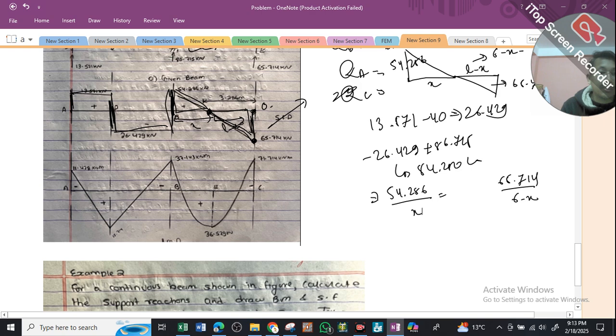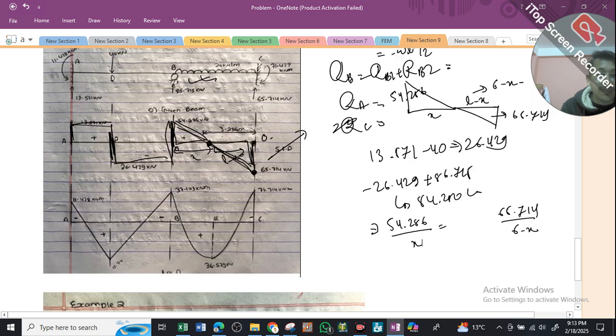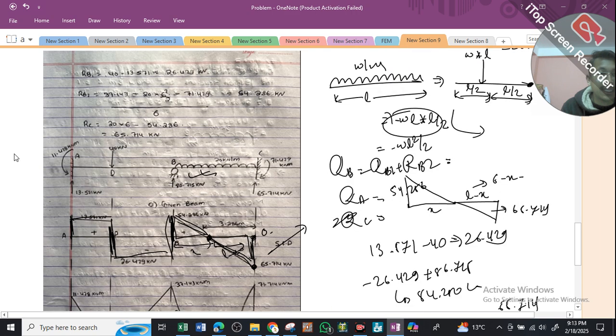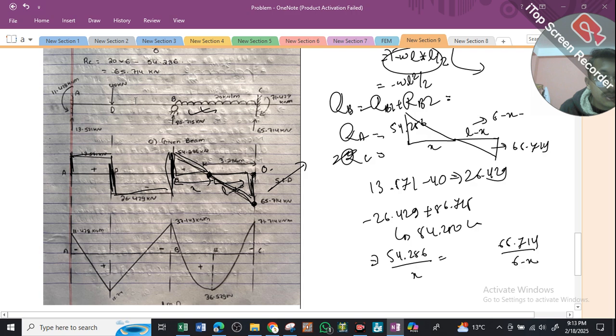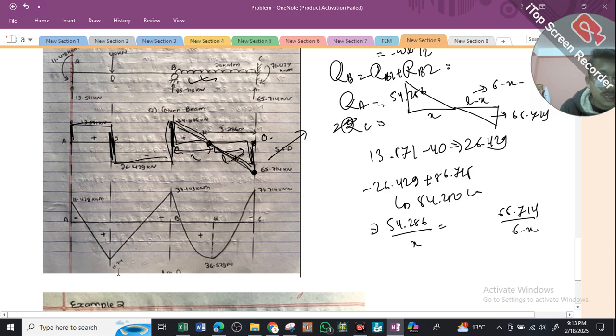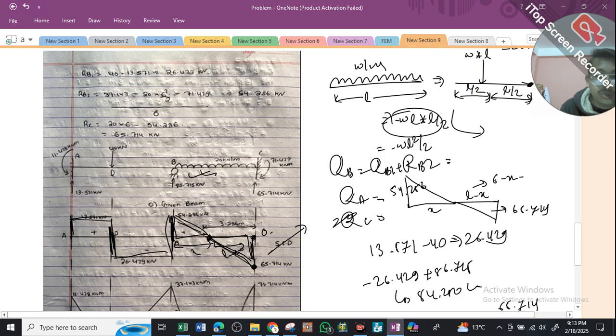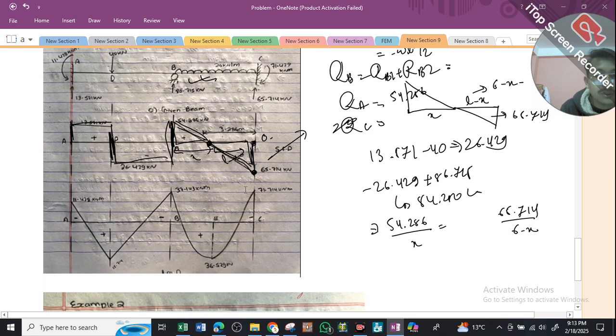The negative we're going to write upward because it is opposite for your bending moment diagram. So we have this moment 11.478 over here, and this is going to decrease to something over here, a positive value. Again, it will increase up to here, 37.143. We have already calculated this value over here, 37.143, and it will end with 71.429 over here. And we need to find our bending moment at this point and this point as well. So this is just really easy.